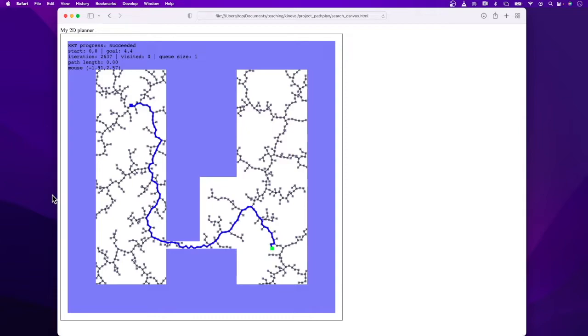And so one important thought that you might be having is that we didn't use the information about where the goal node was in our definition of the RRT algorithm, right? We instantiated our tree at the initial node, and then we just kept extending the tree with disregard for the goal location. There was no heuristic guiding us towards the goal, and no constraint on our extension of the tree that would make it prioritize moving towards the goal. We just continually randomly proposed configurations and used them for the extension.